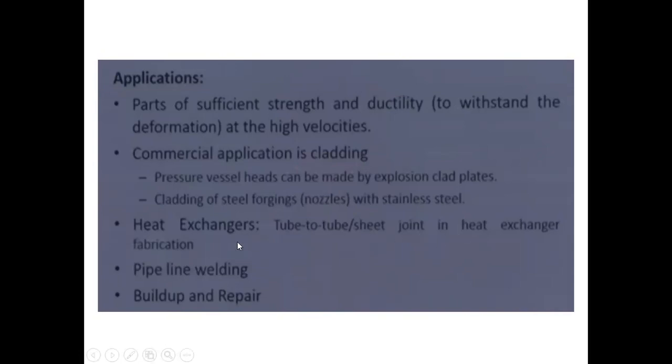A heat exchanger is an equipment in the mechanical industry that is able to transfer heat from one system to another. Those will have tube to tube joints or tube to sheet joints, and that is what is done with the help of explosive welding. Pipeline welding, build up and repair: all these are applications of it. Even for repair reasons, explosive welding can be used.